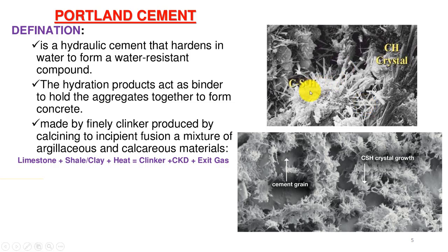Calcium silicate hydrate is a component formed which contributes towards the strength gain of concrete. On the other hand, the ettringite needles impart the setting of concrete. The needle-like structure retards the flow of concrete and hinders its flowability. On the other hand, the flaky or hexagonal structure in the microstructure is basically calcium hydroxide.